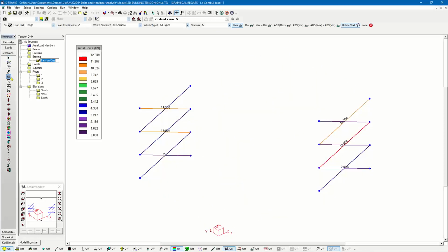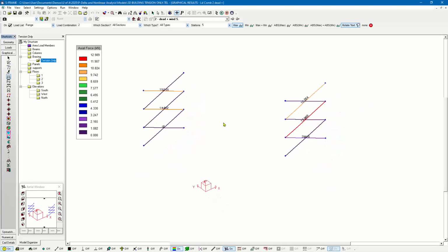And I just want to see here with the axial load diagrams, what sort of magnitudes I'm getting for these axial loads. So you can see in one direction on each side here, we're getting some tension, about 11 or 12 kilonewtons of tension. But if we look at the bracing in the other direction, we have 0 kilonewtons. So we have no negative axial loads, indicative of no compression in these elements. So hopefully I didn't confuse you guys too much with that, me stumbling through the first exercise. This one was the model I should have been working on. But you'll get an idea as you use this in practice.